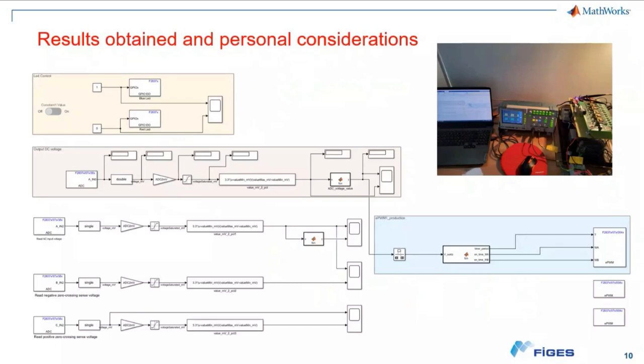This is another study, actually. Shortly I can explain. This is my rectifier, AC to DC converter, and MATLAB integration. It's a hardware-in-the-loop integration. I'm using the Texas Launchpad, and to write the detailed control codes of the Launchpad to control the rectifier, I use MATLAB, and it actually helps me to shorten the time.